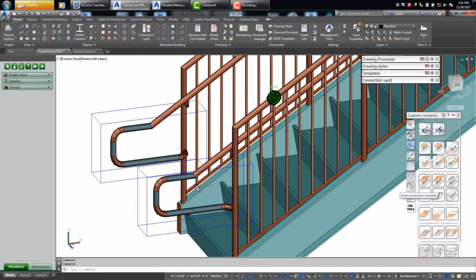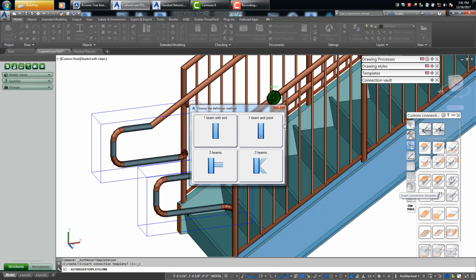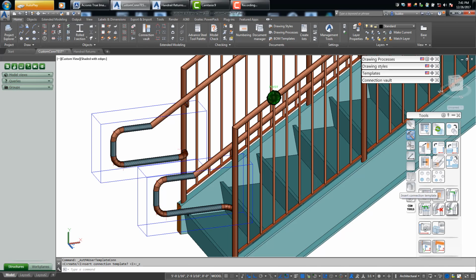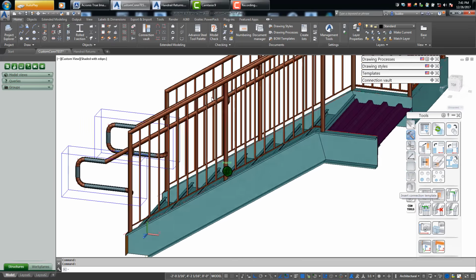Another thing that you can do, which is really cool, is you can take these components and copy them with your parametric copy over here in this group. Basically make it a joint group with these custom components, and if you allow modification, then all the ones that you've copied will actually fall in line parametrically with that modification, and that's a real convenient thing in some cases.